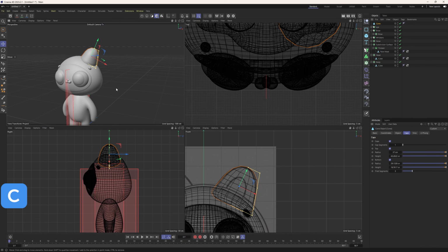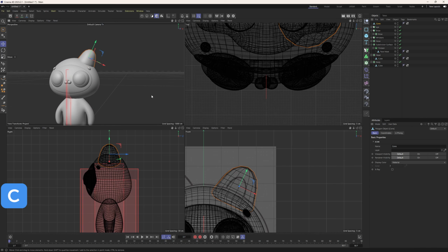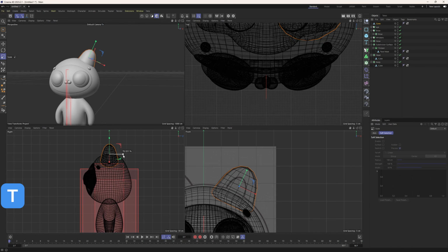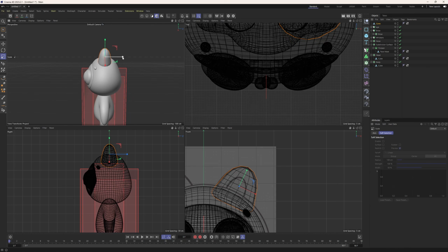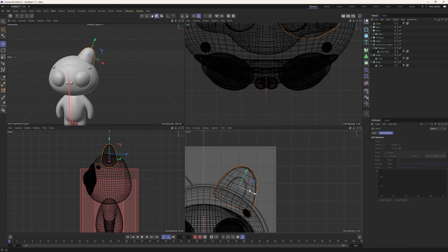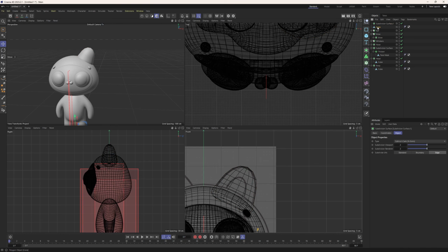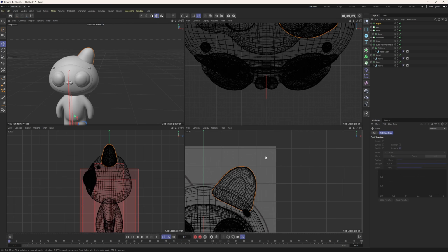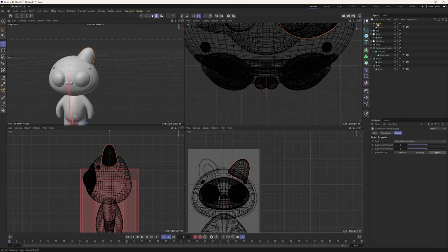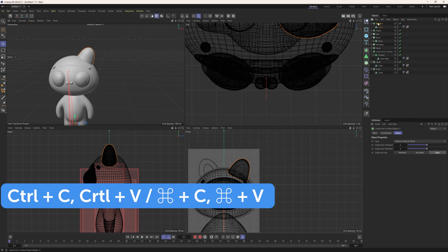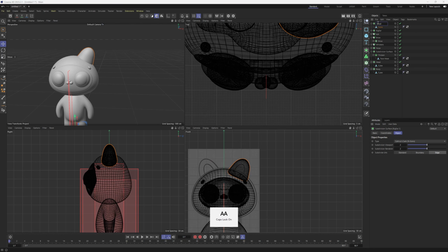Let's make the cone editable by hitting C. It will allow us to scale down the object on the Z-axis and make it more look like an actual ear shape. We put our ear into subdivision surface modifier and rename it as a big ear. Why big ear? Well, next we will duplicate this ear, Ctrl C, Ctrl V, together with a subdivision modifier, and we can call it as a small ear. A small ear because we need to create the inner shape of the ear as well.